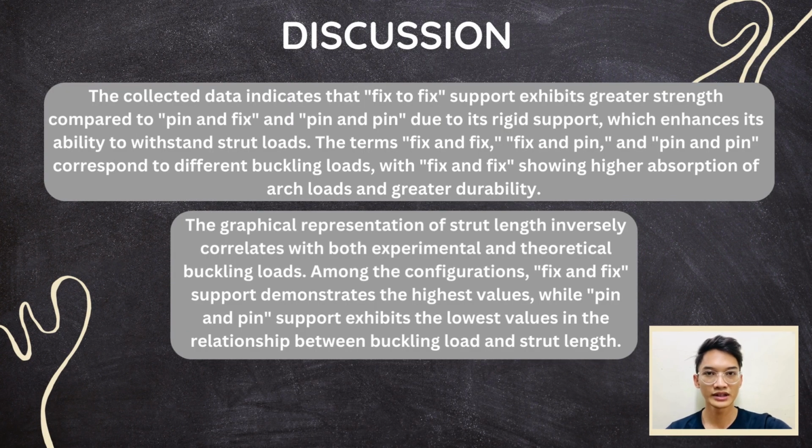For discussion, I can summarize that the fix and fix support is stronger than pin and fix and pin and pin, attributed to its rigid support. The terms represent the buckling load, with fix and fix displaying superior absorption of load, indicating greater durability. A graph illustrates the relationship between strut length and buckling load in both experimental and theoretical scenarios. Fix and fix support shows the highest value, while pin and pin support shows the lowest value between buckling load and strut length.